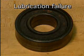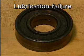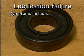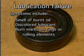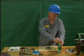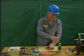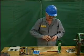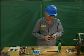Another type of bearing failure is lubrication failure. Lubrication failure occurs when the oil or grease in a bearing fails to function correctly and the bearing overheats. Symptoms of lubrication failure include the smell of burnt oil, discolored lubricant, and burn marks on the rings or rolling elements. Lubrication failure can also be caused by improper lubrication. This could mean too much or too little lubricant, using the wrong kind of lubricant, mixing lubricants that aren't compatible,